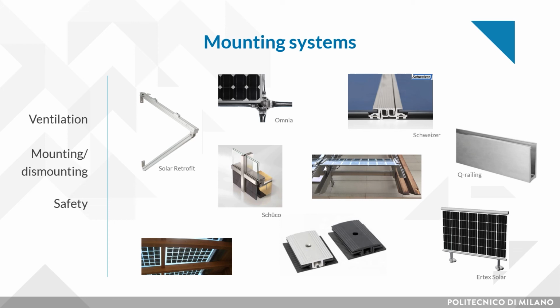What is so important when dealing with BIPV is to consider some aspects. Of course, BIPV has to be functional, safe, and good-looking, as if it were a traditional building component, but let's consider also that it needs proper ventilation, otherwise bad performance and critical problems can occur. It should be easily mounted and dismounted. It generates electricity, so be careful about fire risk.